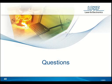Yeah. Cool. And then Thomas had a follow-up question just really quickly. How could we metallize the via hole? What are the options for that? Yeah, there are several options. LPKF has been in the circuit board industry for over 37 years now, and we have a silver plating option, which is a paste that can coat sidewalls, which is great for prototyping. We also have copper plating machines that actually grow copper and bond it with the material using an activation ink and then a copper plating bath. So those are two options.